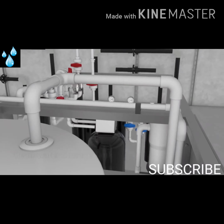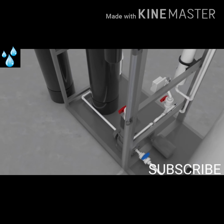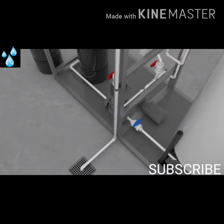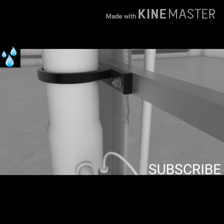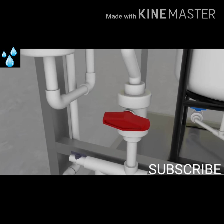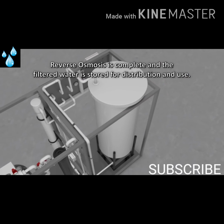At higher salt levels, the concentrate is sent to sanitary sewer, or in some cases non-critical locations for reuse, also known as gray water recycle. In higher water recovery applications, a small percentage of the concentrate water is sent back to the inlet of the RO membrane for recycle. The salt removal reverse osmosis step is complete, and the filtered water is stored for distribution and use.